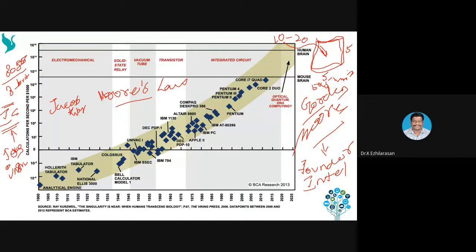No, it's not possible, because if you keep on adding transistors, one point comes up. If you're taking one transistor, the key factor for the transistor is simply the aspect ratio, that is W by L, the width of the transistor and the length of the transistor. So you need to do the scaling of the transistor, then only you can accommodate it in an IC.